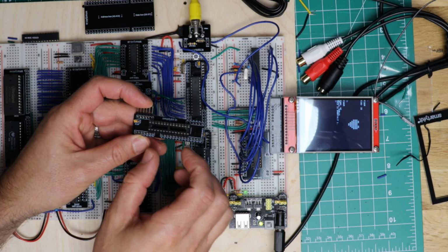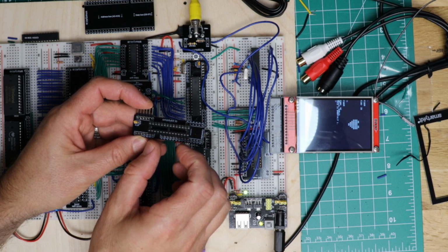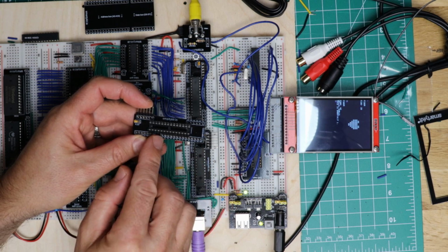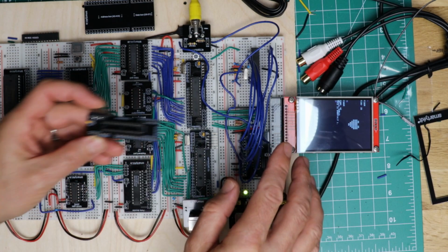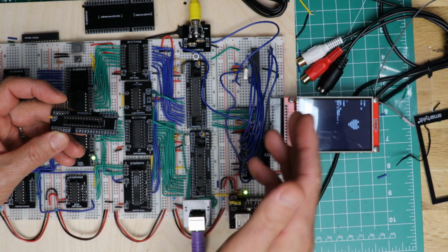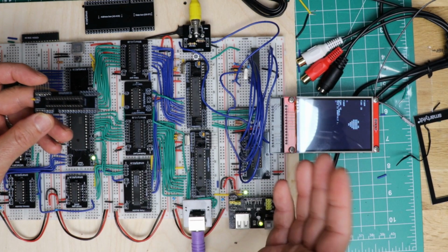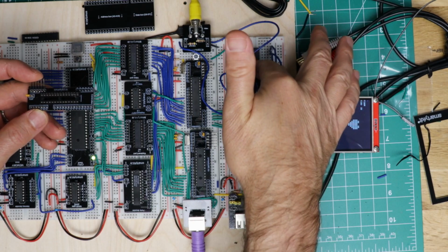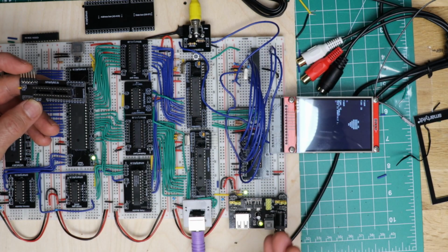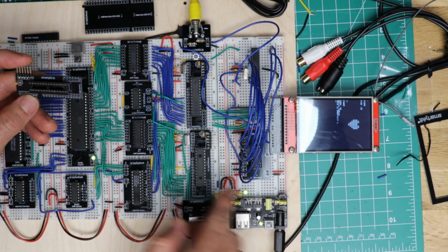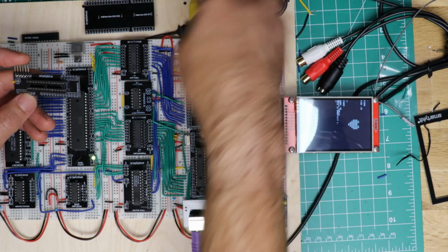And that means that the data coming out of port D on this will not work because these three are shorted out. So you'll never get a proper RF data out. The screen itself will work because it's self-contained, and this chip over here, which is the high-res driver that generates the sync signals and so forth, shifts the information out to the shift register, which then puts it out into the data line.